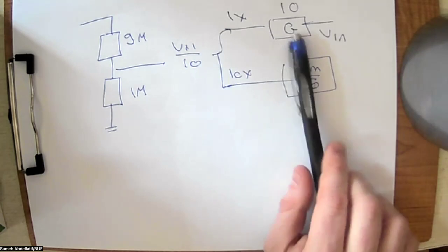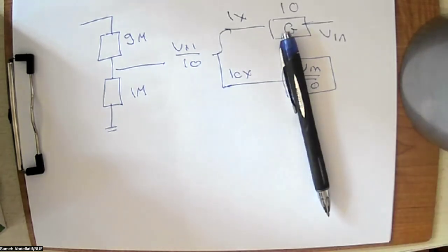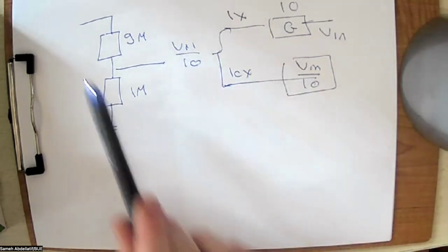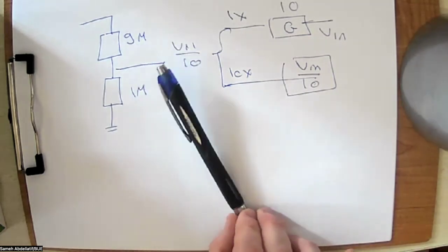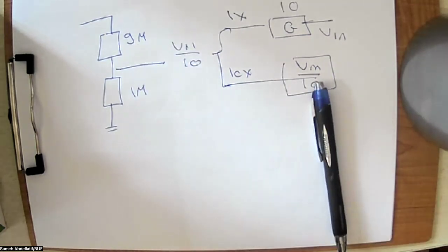So the 10x mode enables you to still measure voltages which are much greater than your amplitude limitations, because you are using this voltage divider to attenuate the input voltage by a factor of 10. So what you are measuring here is simply 10% of the signal, not the whole signal. That's why we keep this as an added value for our oscilloscopes.